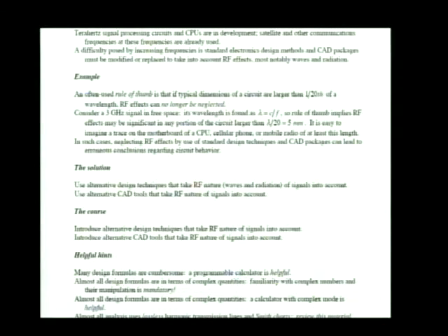Okay, that tells me that if I'm trying to design a circuit that has a typical dimension of more than 5 millimeters, I better use ADS software and not PSpice. And I better apply S parameters to the circuit analysis rather than just using plain old Kirchhoff's voltage law and Kirchhoff's current law. These are the things we're going to learn in this class. 5 millimeters. That's pretty darn small.